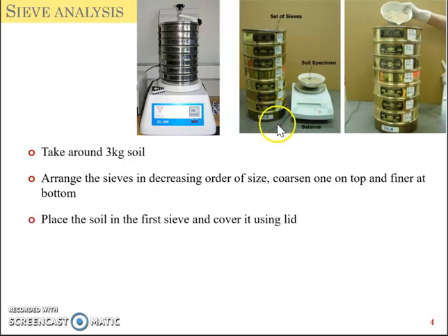Then you can place the soil in the first sieve and cover it, and then shake the entire assembly for about 7 minutes.